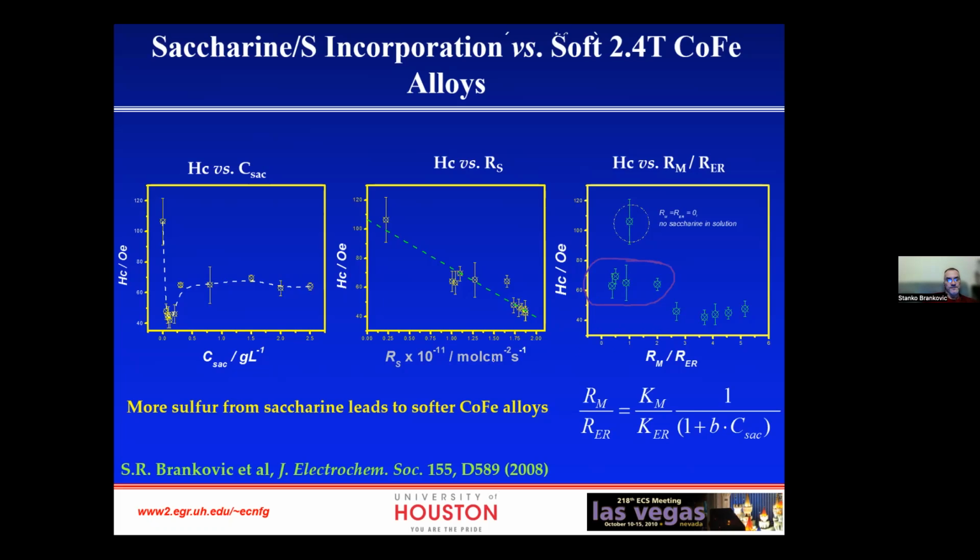That's number one. And number two, more additives decrease the stress, but at one point start to hurt you because they will start building up corrosivity. And the last thing is that more additives make the alloys more susceptible to corrosion, if we are just looking at the corrosion potential discussion.